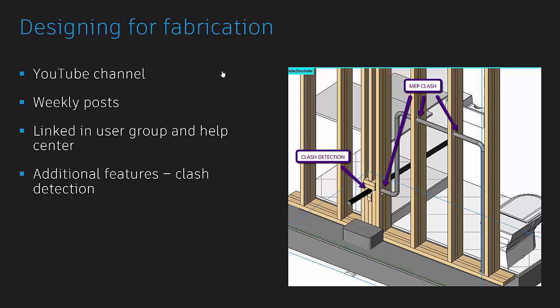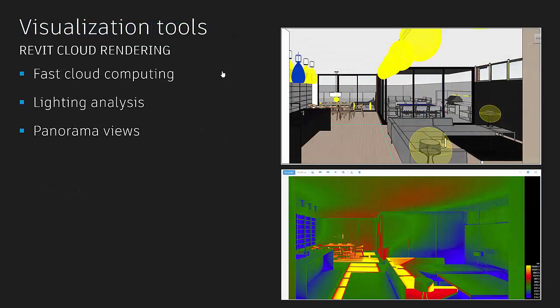It's even got a clash detection tool. So one of the team members was helping out looking at how we were going to run some of the pipes through the walls, and we can work out where things might be clashing and when we need to double up some of the timber works. So a great tool to check out if you're wanting to move into the future and deliver proper building information modeling data.